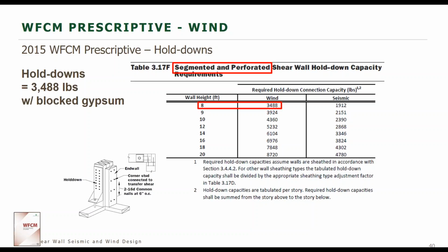And in the wood frame construction manual, if you go to the commentary, we keep referring to that a lot, it shows the 0.6 adjustment factor to go from the 700-year return ultimate loads to ASD loads that are then used in the wood frame construction manual.